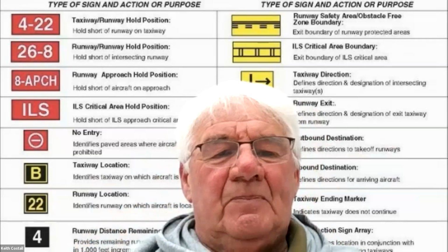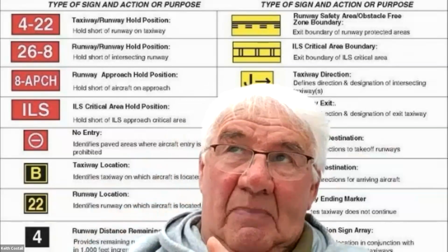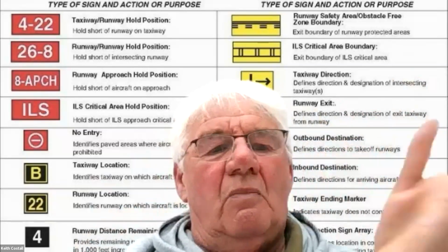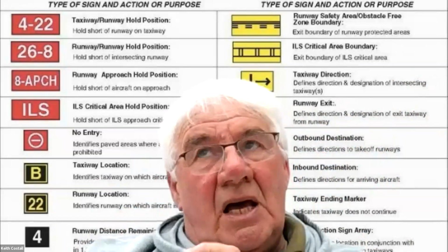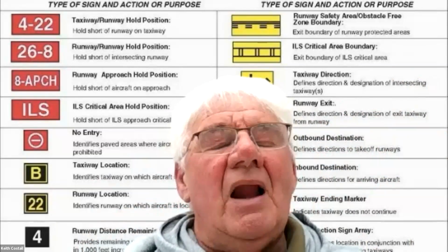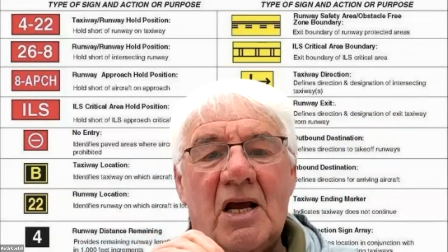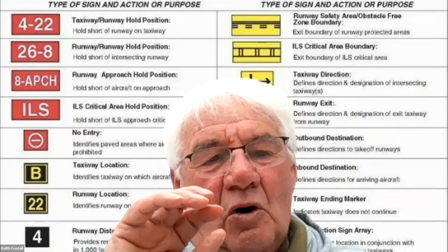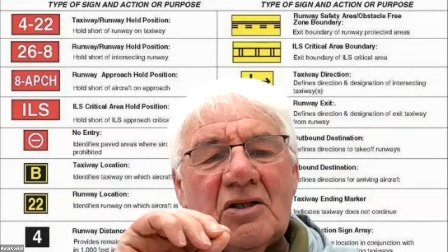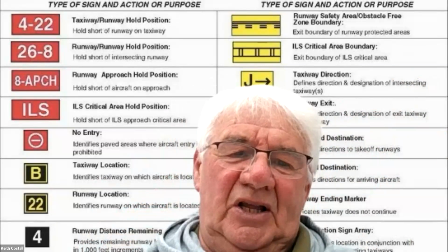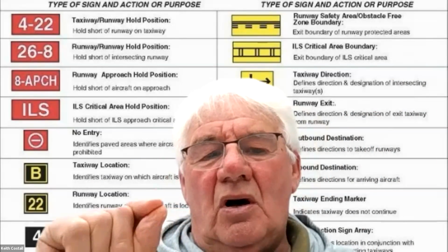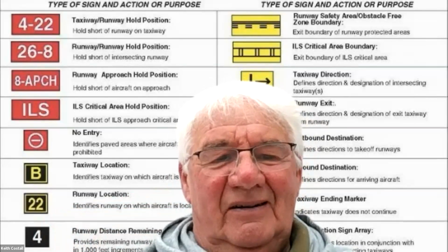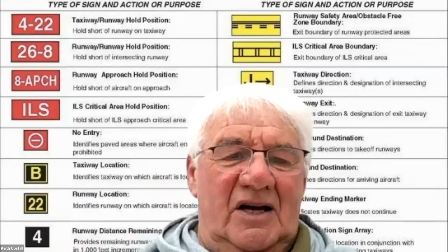So principally, when we look at PAPI number 2 or PAPI B, which is the third out from the runway, that's the first time that a pilot knows visually they are below the glide slope. And therefore, if we're measuring, what tolerance should we be including in there? Because when I go around the world, I see different tolerance levels being put in for the maintenance guys.